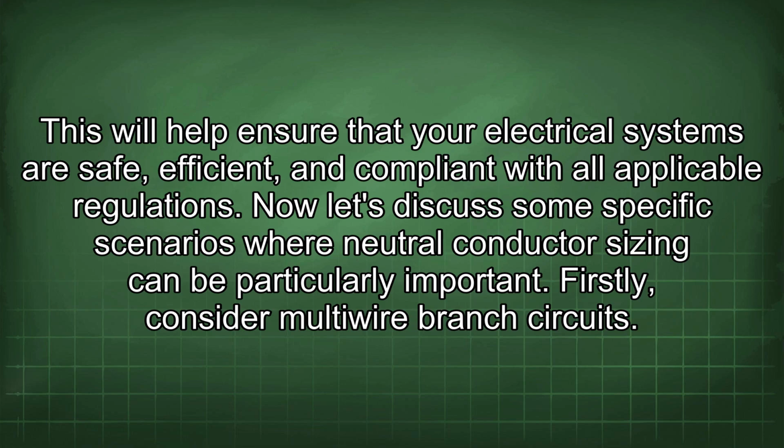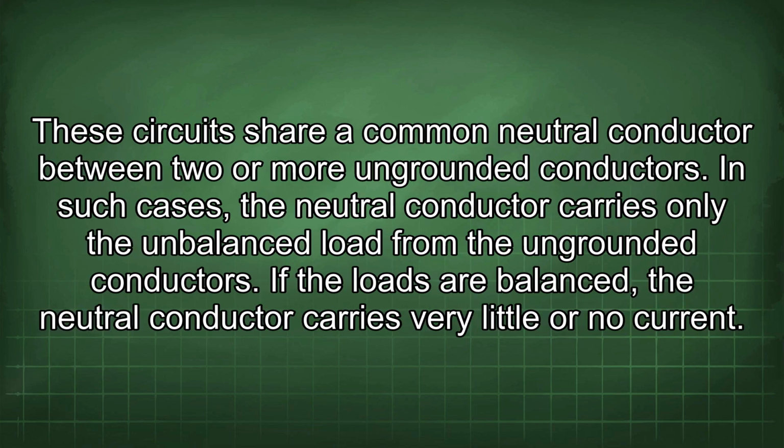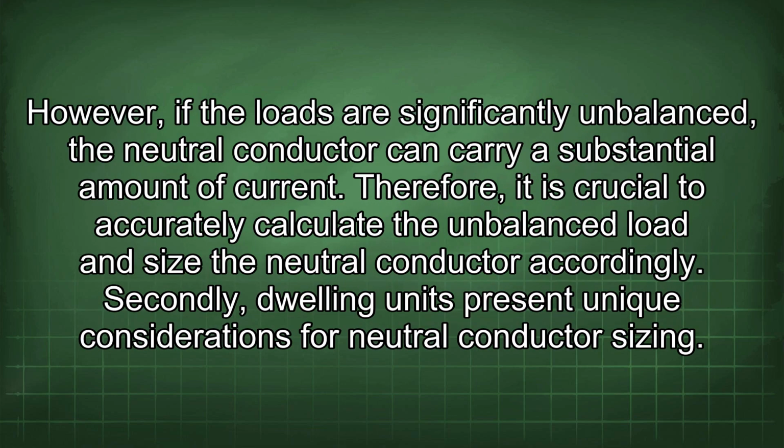Now let's discuss some specific scenarios where neutral conductor sizing can be particularly important. Firstly, consider multi-wire branch circuits. These circuits share a common neutral conductor between two or more ungrounded conductors. In such cases, the neutral conductor carries only the unbalanced load from the ungrounded conductors. If the loads are balanced, the neutral conductor carries very little or no current. However, if the loads are significantly unbalanced, the neutral conductor can carry a substantial amount of current. Therefore, it is crucial to accurately calculate the unbalanced load and size the neutral conductor accordingly.